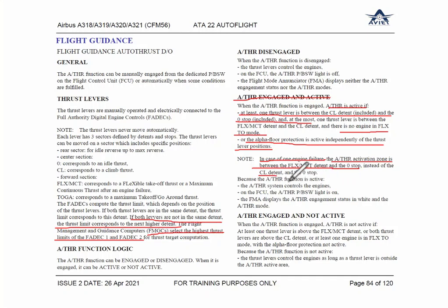Since the auto thrust is active, your auto thrust function will be controlled, that is commanded by the FMGC. You will have a light on the switch. The FMA will display auto thrust in white color.